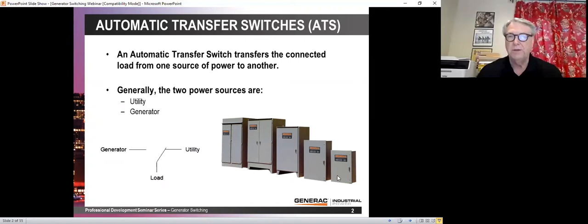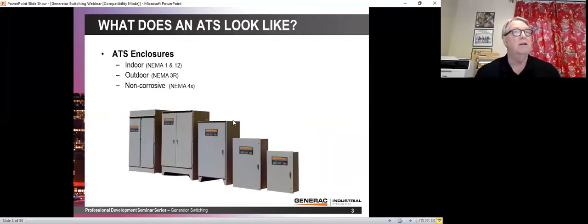These are some of the transfer switches, as you can see on the right. This one on the right looks more like a 100 amp NEMA 1 switch. The one on the left is a NEMA 3R switch. You can tell because they have the bolts around the door to make sure that the gasket is fully sealed, and they've got the rain hood and so on. Generally, NEMA 3R switches are not that much more than a NEMA 1 switch, maybe $100 up to $300 or $400.